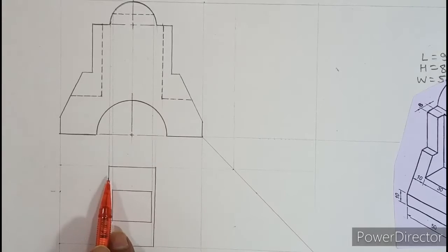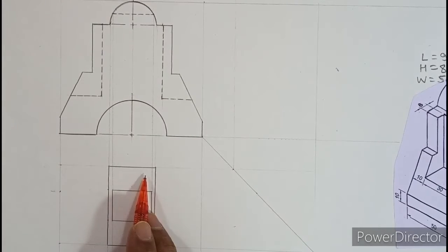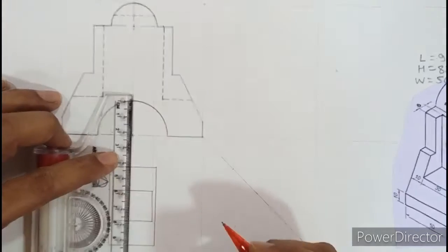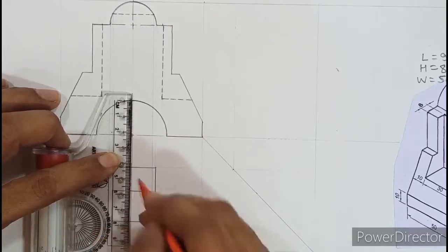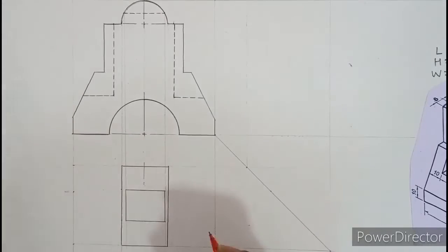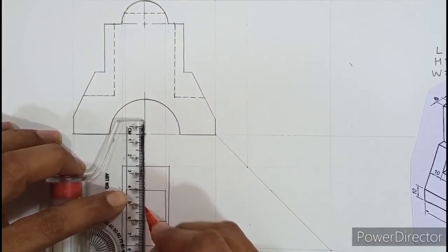As I told you, this surface is round, and in graphics, whenever you draw an orthographic, a rectangle without an axis implies a flat surface. If you don't draw an axis, the reader will feel that it's a flat surface. Therefore, aligning with the previous line and extending just a bit, about 50, we can draw the axis line, which represents that the surface is circular.